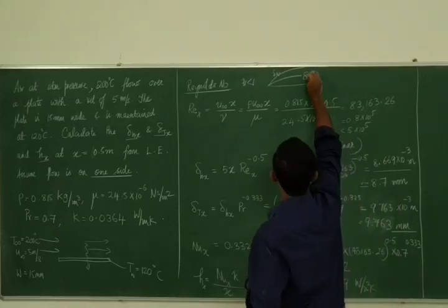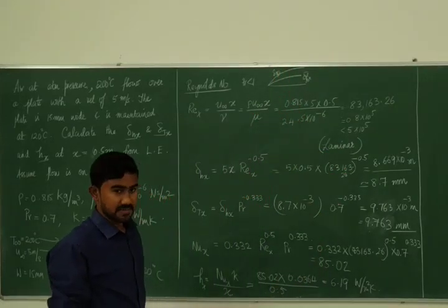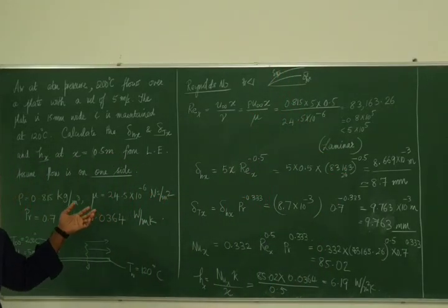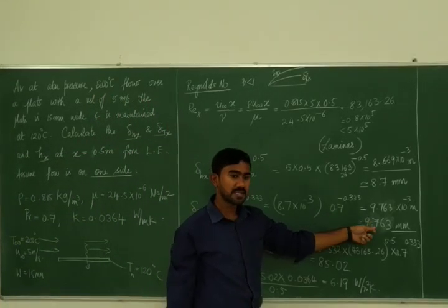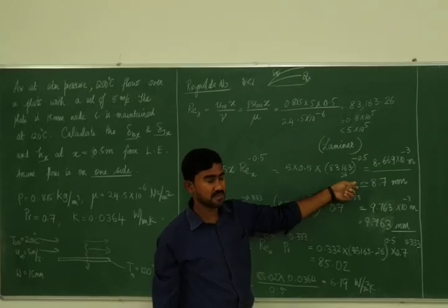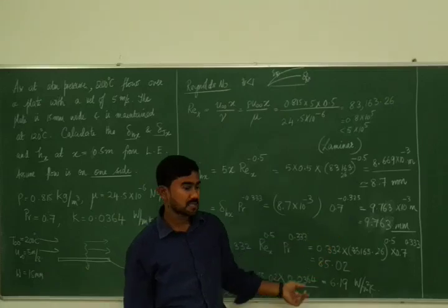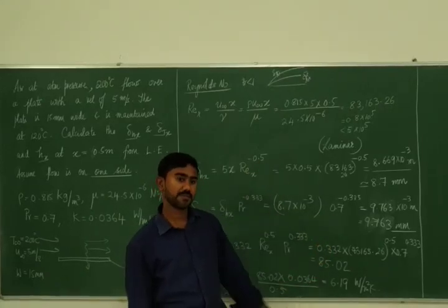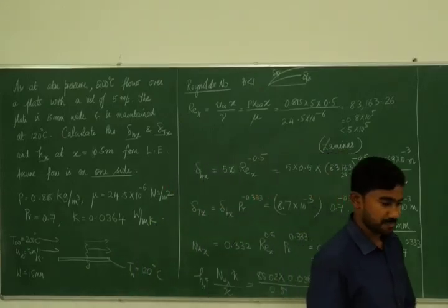So it's the opposite way. The hydrodynamic boundary layer is thinner and the thermal boundary layer is thicker. This is true when Prandtl number is less than 1. Sorry for that. When Prandtl number is greater than 1, it is the other way: the thermal boundary layer will be thinner and the hydrodynamic boundary layer will be thicker. All the other answers are perfect.